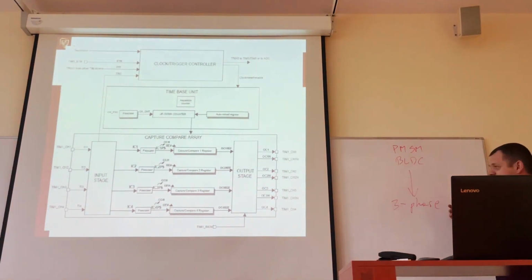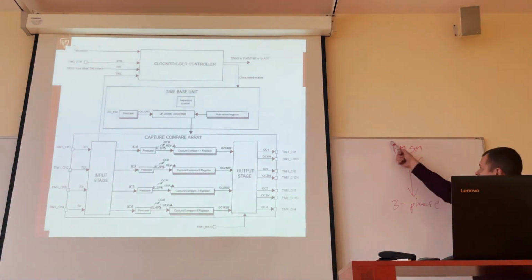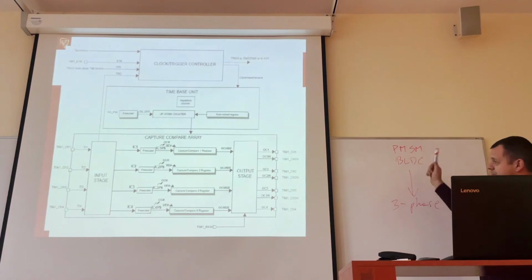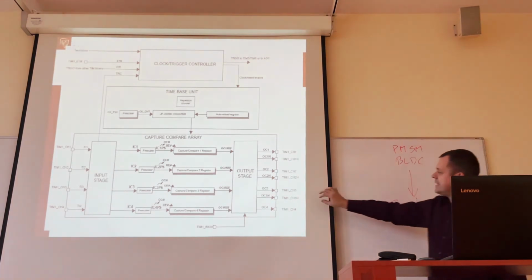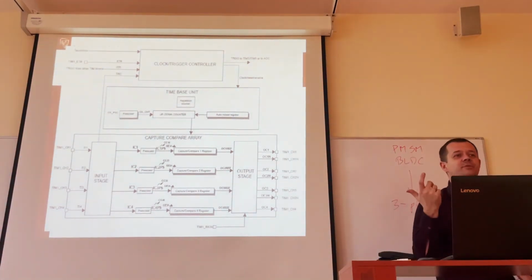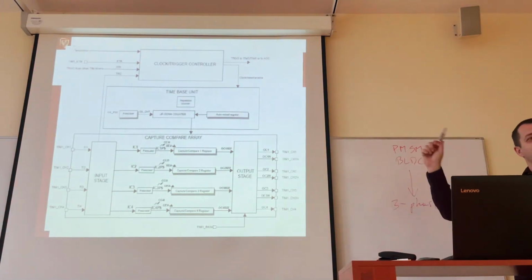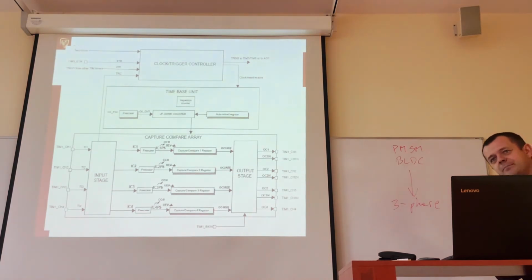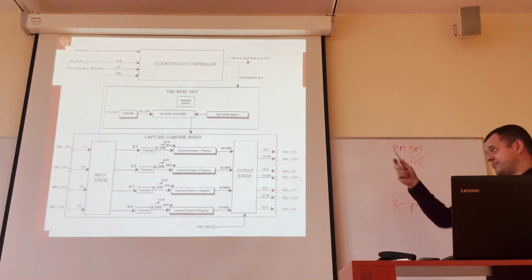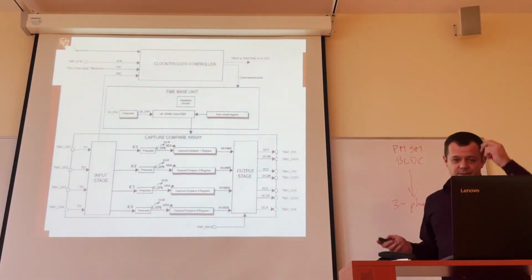Everybody knows, I think, standard three-phase motors that we can supply from the AC mains. But in the digital world today we are using direct drives, which are basically the so-called brushless motors as well. They are in fact three-phase, and they need three such pairs, three H-bridges, to be driven. Microcontrollers today support it directly. So we have timers with three such outputs, so that we can connect three bridges and drive such a PMSM motor directly from a microcontroller. That's also the reason why we have three outputs here.